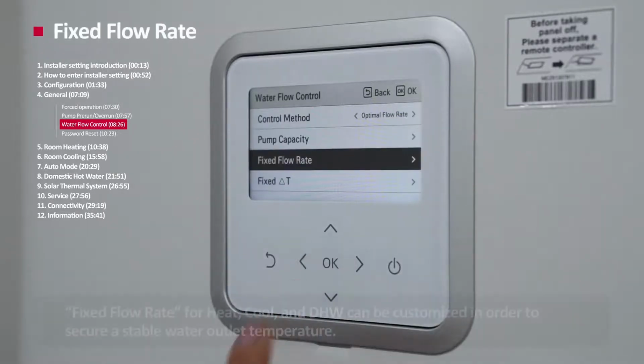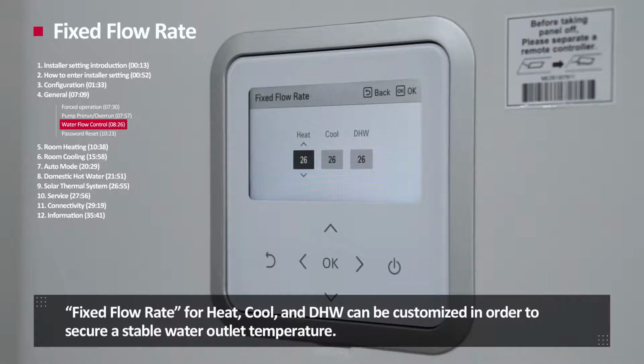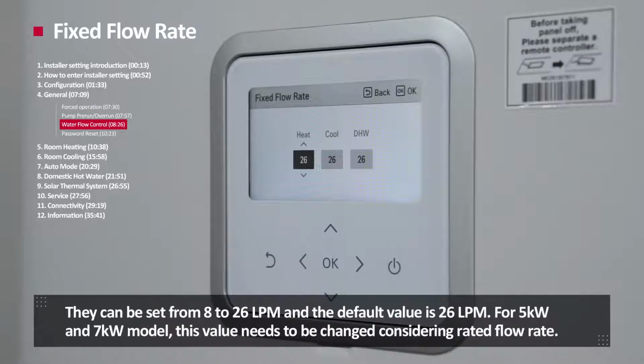Fixed flow rate. Fixed flow rate for heat, cool, and DHW can be customized in order to secure a stable water outlet temperature. They can be set from 8 to 26 LPM, and the default value is 26 LPM. For the 5 kW and 7 kW models, this value needs to be changed considering the rated flow rate.